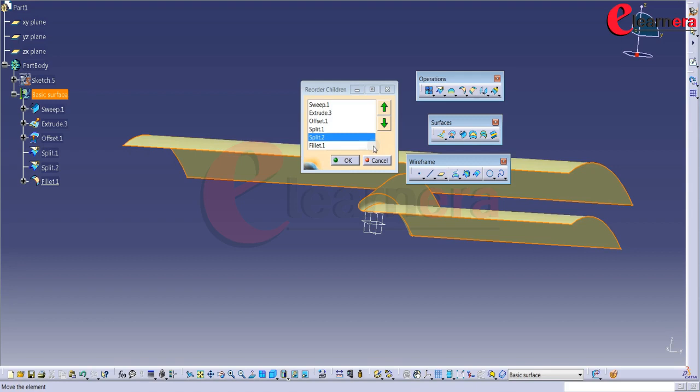What are the advantages and disadvantages of using ordered geometrical set? First, see advantages. Elements in this set maintain linearity with respect to their order of creation, which follows a simple design process. It consists of wireframes, surfaces and solid body.